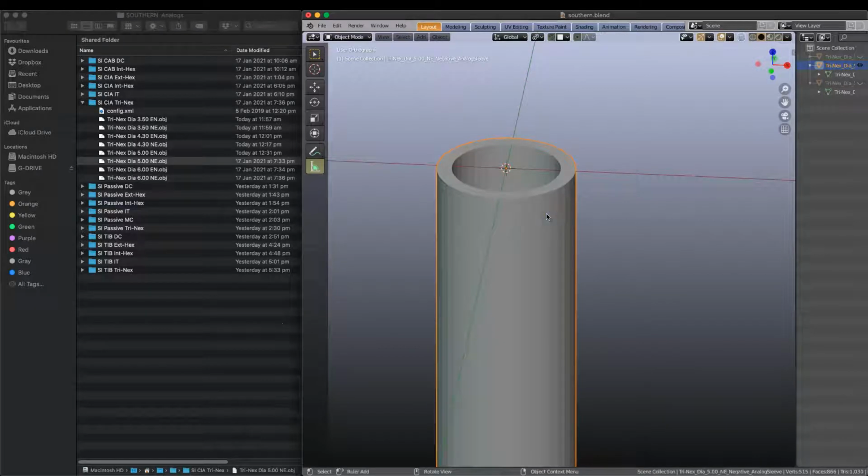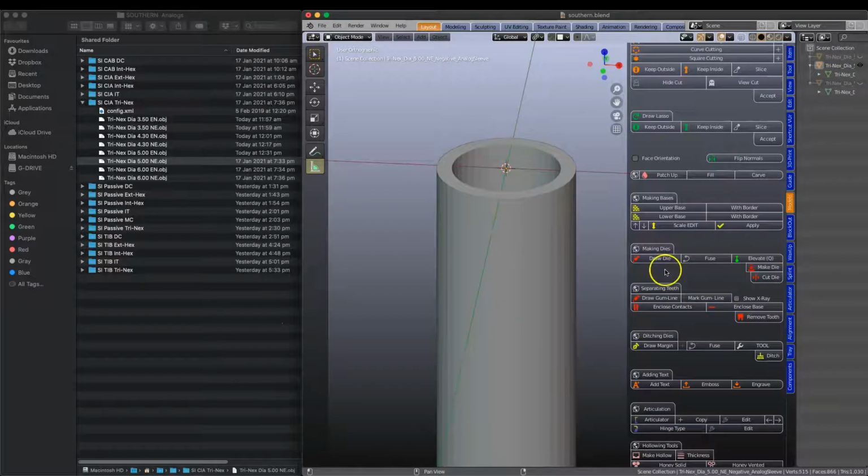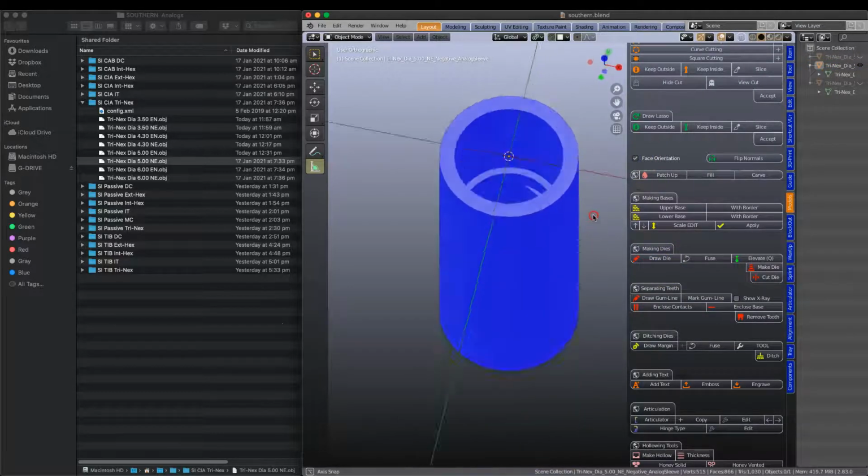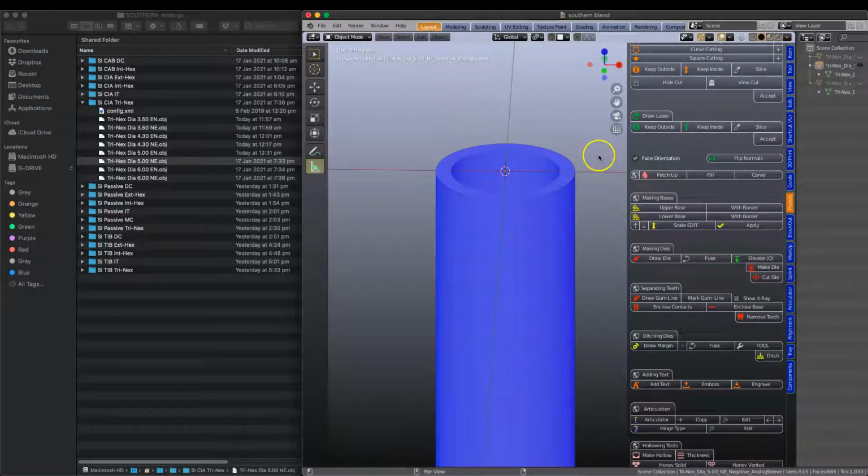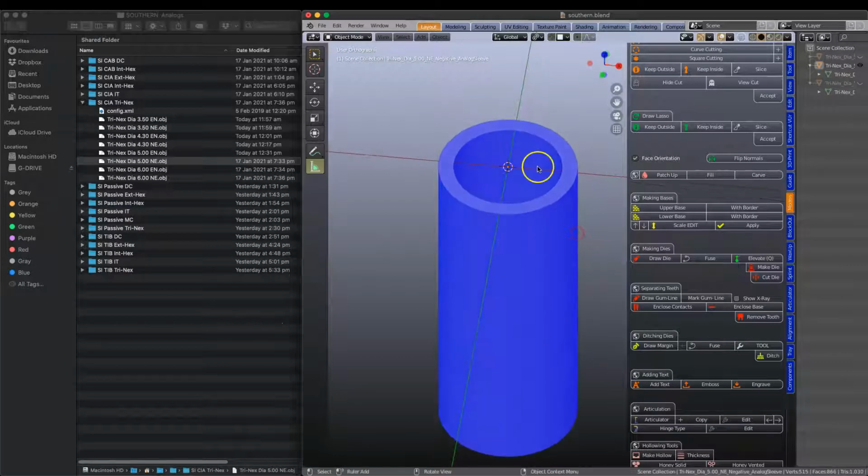If I go into the model designer now, press the N key and press face orientation, all of the vertices, the normals, are in the correct order. Initially when we started, the red would be on the outside, which is okay for other CAD software where they're going to just connect the mesh geometry onto the scan and then make a model.